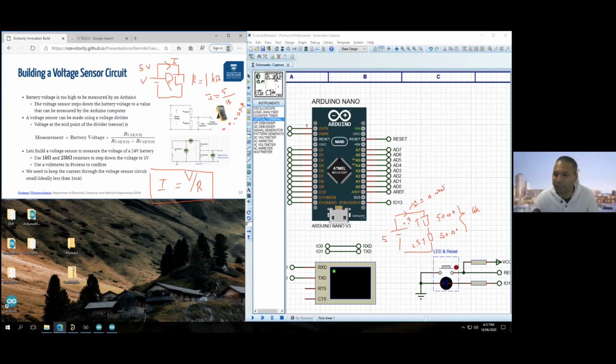It's still 2.5 because you added a 0 here and a 0 here, right? They cancel out. So regardless of how many zeros you have in this resistance, or whether you divide this by 10 or 2 or whatever, as long as they are equal, this voltage is equal across each of them, because the current going through them is the same. So is there any value in having resistors with higher ohmage? Yeah, so that's why I'm explaining here.